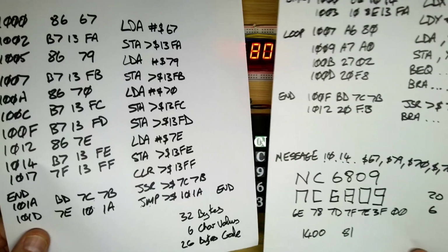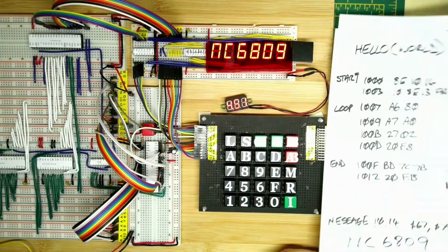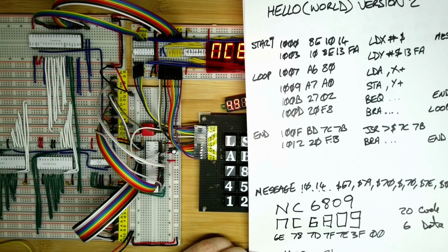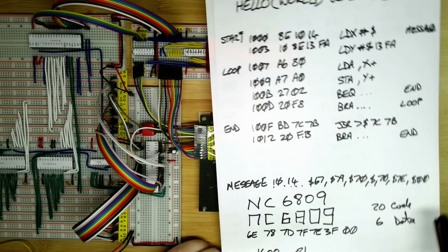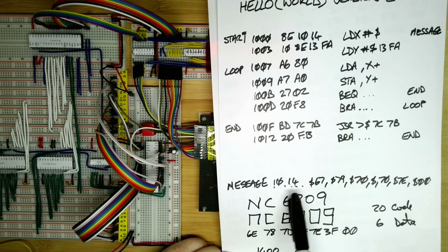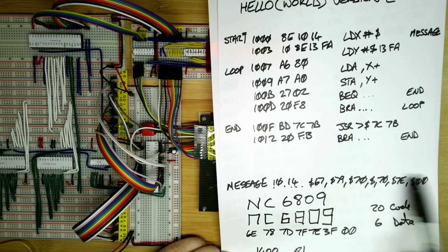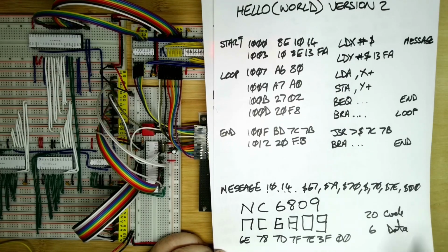So I think you can see that this approach is a little bit more efficient, and the only thing we probably would need to consider would be having a length, perhaps, because we need to use the 7 segment data. We probably need to do this more by having a length as the first byte, perhaps to say only do this number of bytes, and that way we can have zeros and blanks embedded in the data. But it was an interesting way of doing this, just to show the idea here.